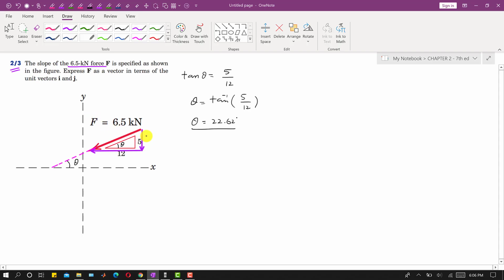So this is f of y component and this component is f of x, right? And we know this angle, right? So this angle is theta. So now from this triangle we can say that the force F is making angle theta with f of x. So we can write that f of x is the cos component directly. So I will write that f of x is f cos of theta, and this f of x is acting in the negative x direction, so I will write minus,